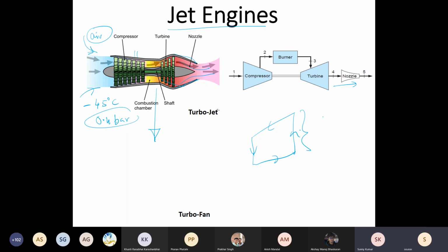You don't require heat exchangers now, because there is no secondary fluid. Your air itself is the working fluid, and once you cool the air, you don't even need this process line to close. You get the cold air and directly blow it into your cabin. Lesser number of devices, better it is for systems which are in motion.